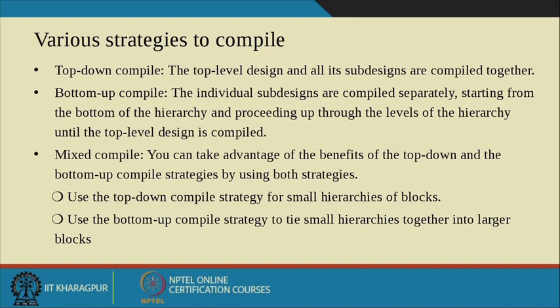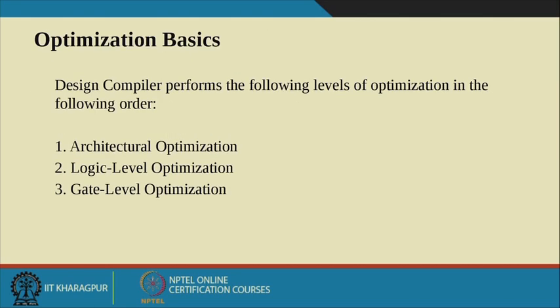In mixed compile mode, you can take advantage of the benefits of both the top down approach as well as the bottom up approach, by using the top down compile strategy for smaller hierarchical blocks and the bottom up approach to tie up those smaller hierarchical blocks to create a larger block. Okay, so these are the various strategies for compiling in Design Compiler.